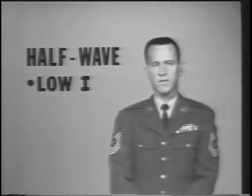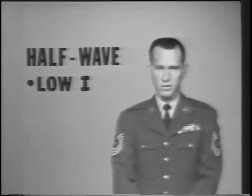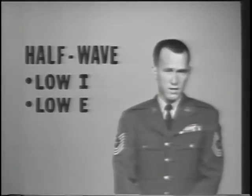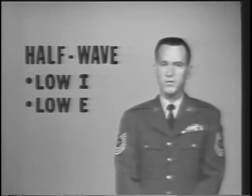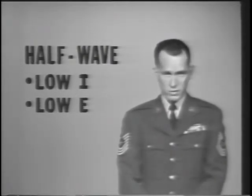The half-wave rectifier is limited in the amount of current it can supply to the external circuit. Additionally, its average DC voltage output is less than 1/3 of its peak secondary voltage. For these reasons, its use is limited to very low power applications.